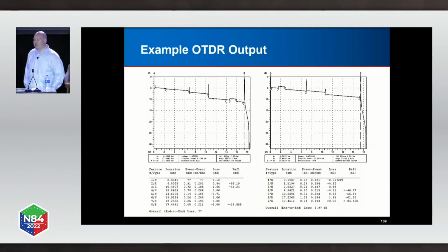So here's an example of an OTDR output and what it looks like. You see the loss, and then you see the places where there's events. Actually, this is an example where it should be a nice steady loss, and then you see it go up and then come back down. That's what's called a grower. This was an example of a mismatched core type. This was like AboveNet from 20 years ago, so probably why. But that's an example of what you'll see on an OTDR.